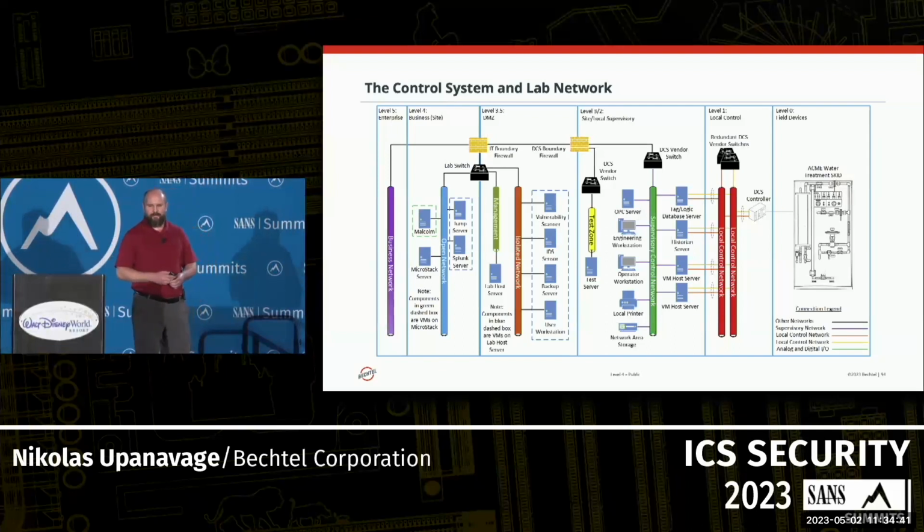Common to most of these distributed control systems is that you have a tag logic database server. It's where all of your logic sits. You have your different function blocks and points, and the engineering and operator workstations will interact with that server to either download logic to the controller or to do a variety of activities. This system also has virtualized servers, so a lot of our engineering and operator workstations are virtualized.